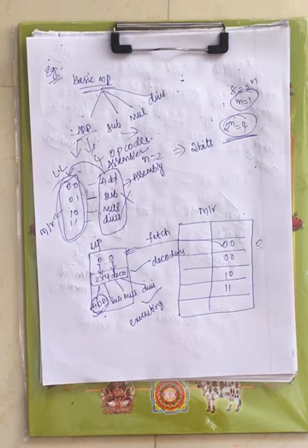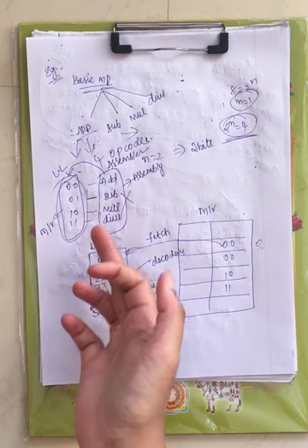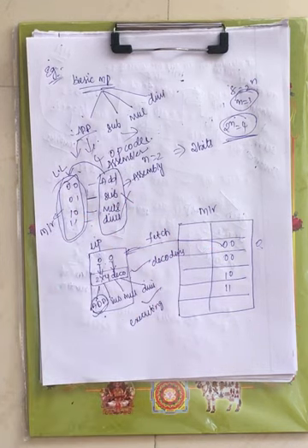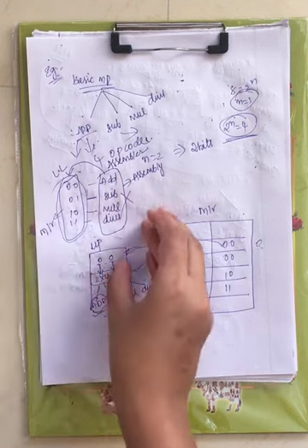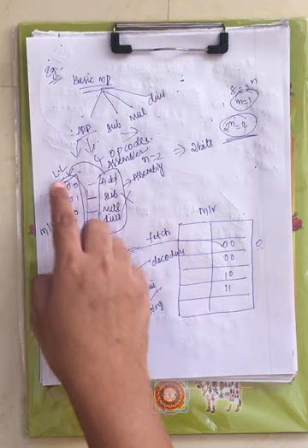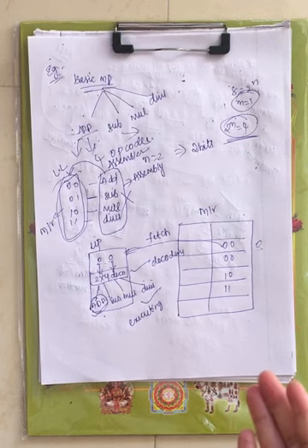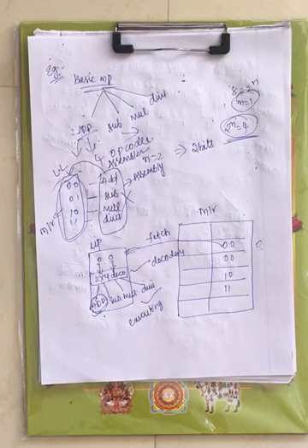You have 4 instructions, 4 opcodes, and the opcode will be of 2 bits, right? After converting assembly language to low level language, these are the possible opcodes. For 2 bits the possible opcodes are 00, 01, 10 and 11, right? You will have a different opcode for each instruction. We are just assuming this particular opcode is for this one, and this particular opcode is for that. You can't directly store assembly language, you store this low level language in the memory, right? What the processor will do is first fetch the instruction. Fetching the instruction is nothing but fetching the opcode, the binary form of instruction.